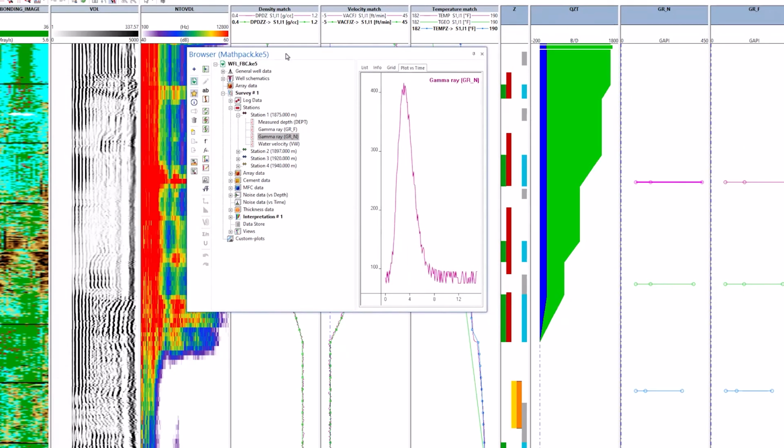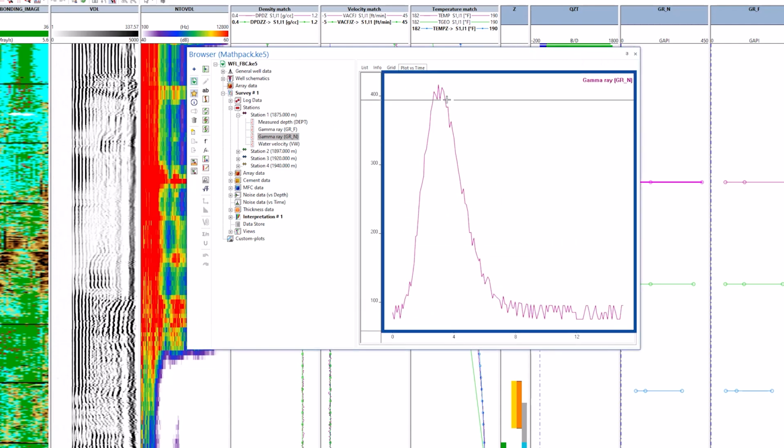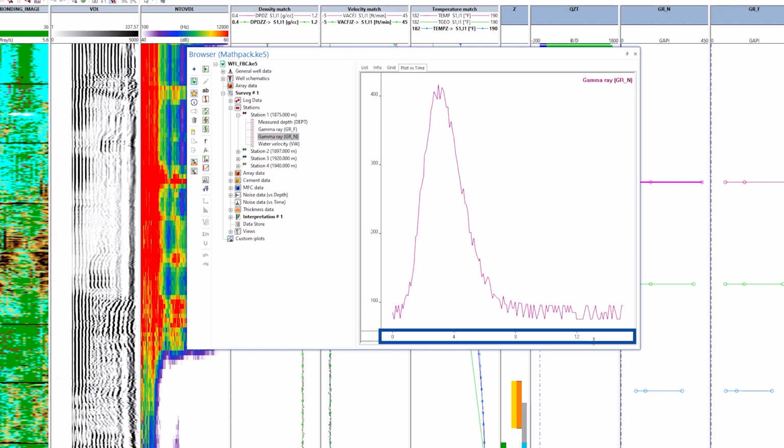As the PNL tool contains a multiple gamma ray detector, it is possible to estimate the water velocity by identifying the time to the peaks and the distance between the source and detector.